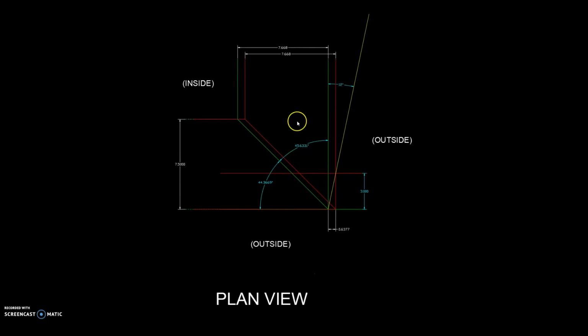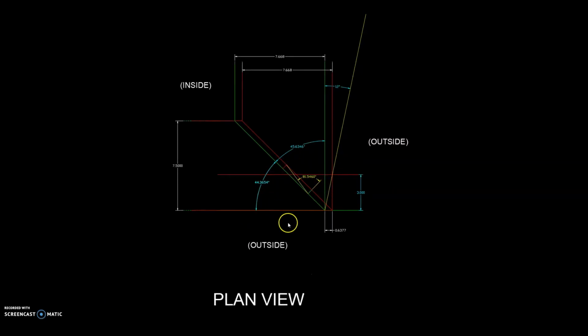To record that in a clear way, we're going to make a vertical section perpendicular to the miter lines, as long as it goes perpendicular to these 2 lines, which are the miter lines contained on both the bottom and the top footprint, and project that down onto the layout to see and measure the tilt. Here we can see the section perpendicular to the miter lines already projected onto the layout.